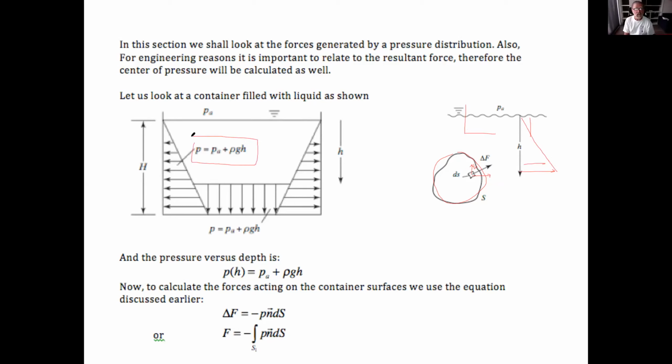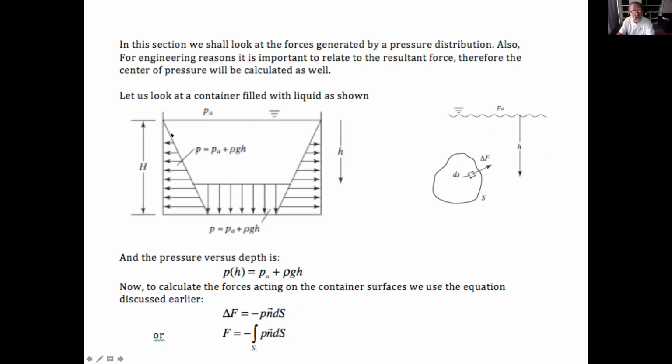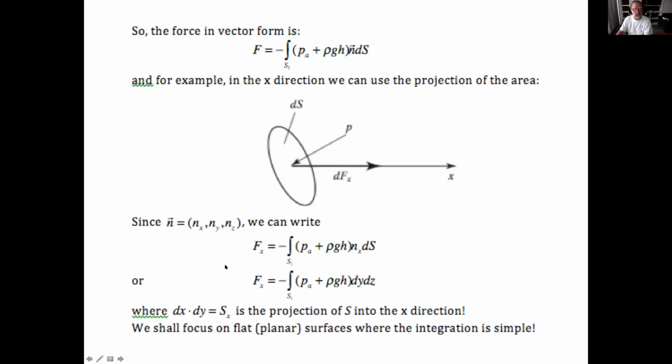Therefore, the forces on the side are changing as well, while the forces on the bottom, if we take just a simple rectangular shape, on the bottom, if it's the same depth and it's flat, then the forces are going to be the same, which is P_A plus rho g h. So very simple.